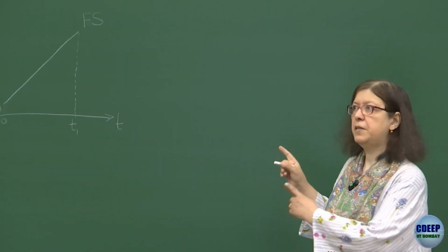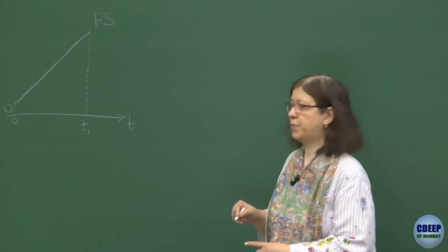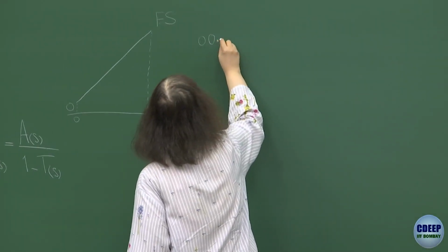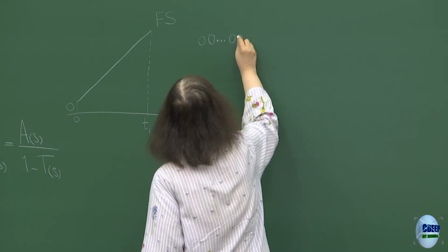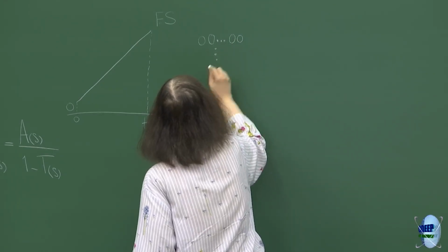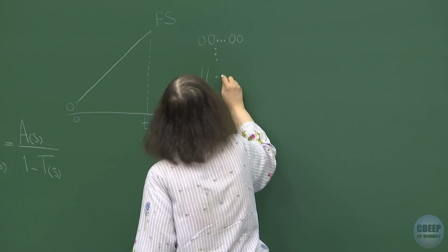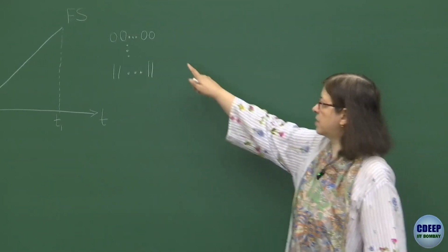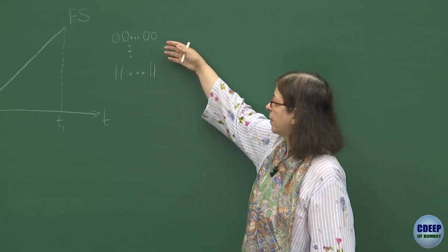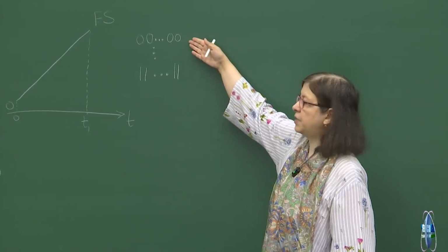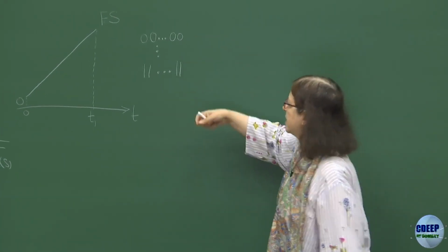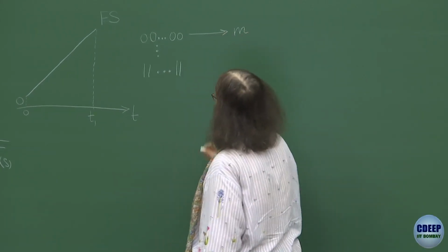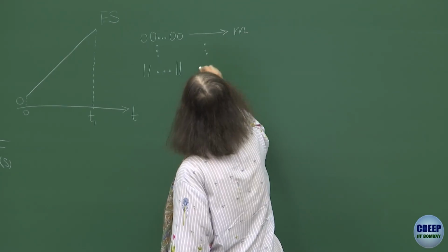Now if we give it to an ideal ADC, for every code starting from all zeros and going to all ones, the number of codes generated for every corresponding word is the same, right? So if you have, for example, m occurrences of the all zeros code, it will be the same for all.